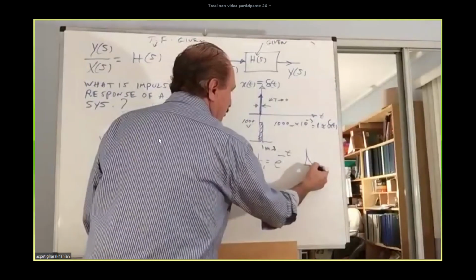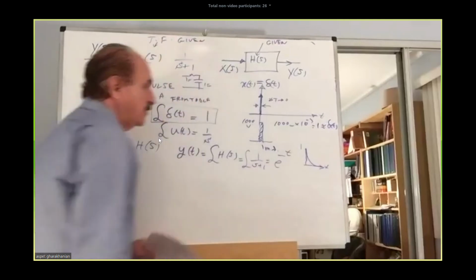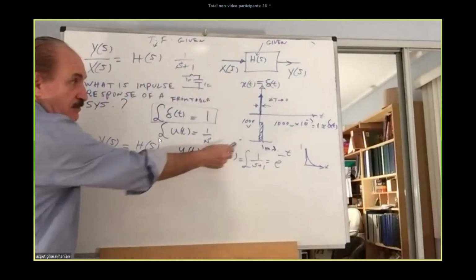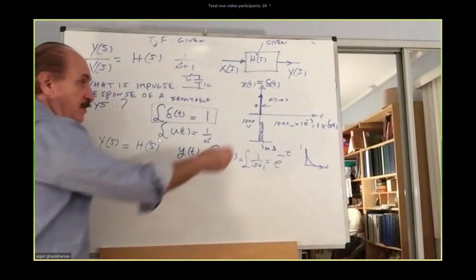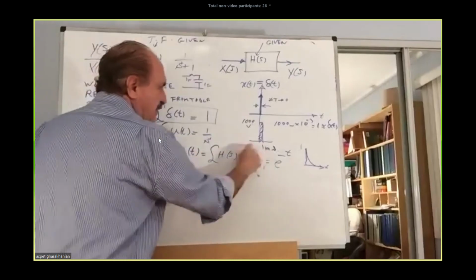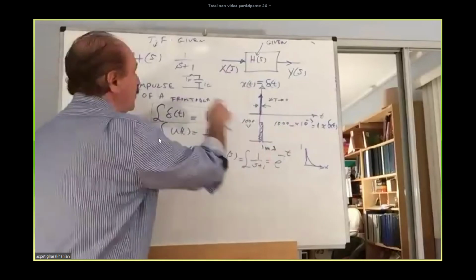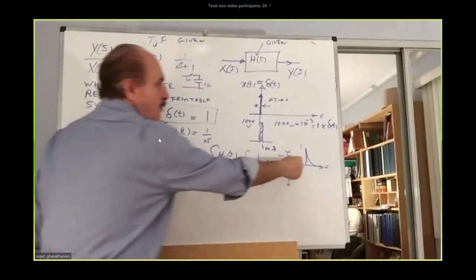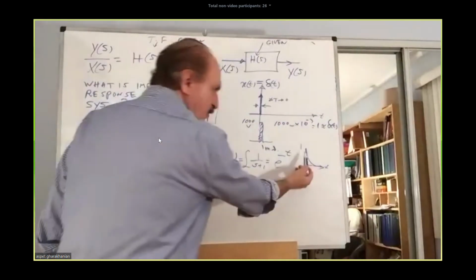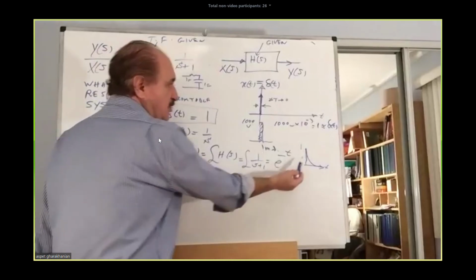That going down to 0. It will rise to 1. If you could apply a unit impulse to that circuit, this voltage. If you apply 1000 volts for a narrow duration of 1 millisecond, the approximate solution to the output of the RC circuit would be, boom, a spike like that, exponentially decaying. Decay time will be pretty slow in comparison to 1 millisecond, because the time constant is 1 second here.